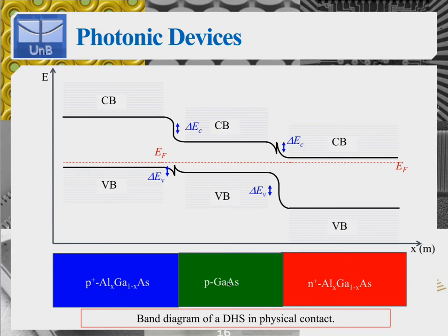It is at a larger electrostatic potential V, but this means a lower potential energy, so this whole band diagram here has moved down. In the junctions, the bands have bent, right, with the S shape that we've seen before, and also considering the potential barriers that were there originally, they're still there.